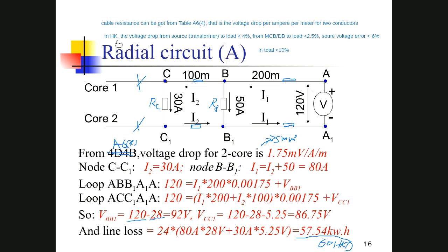That's why in buildings, for most single-phase users, the standard voltage is 220 volts, but the loads should be able to work when the voltage is between 200 and 240 volts.